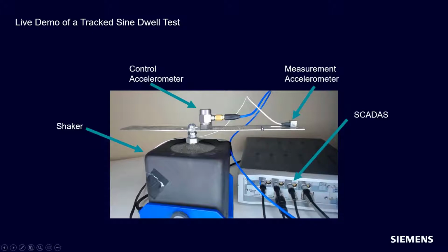They either pop off, the solder points loosen and fall off, or the strain gauge itself just falls apart. Those thin foil type strain gauges. So that's why we use either an accelerometer or more typically a point laser at the tip of our cantilever beam to measure what our displacement is.